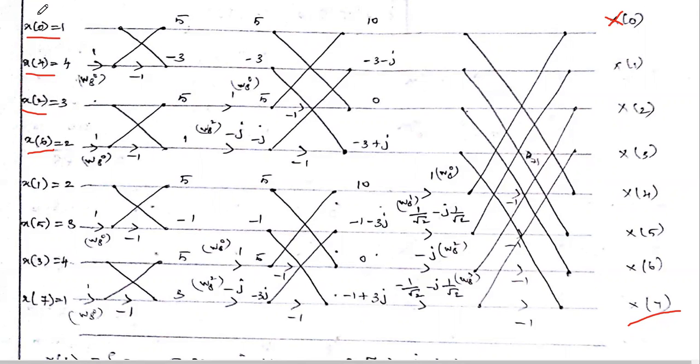How to remember these numbers, and in which index number we have to apply them? I will give the link to that video in the description box, so if you want to listen, you can go and listen. Here, the first 4 data in those 8 lines are the even indexed values, and the next 4 lines are the odd indexed values. So you see 0, 4, 2, 6, 1, 5, 3, 7.